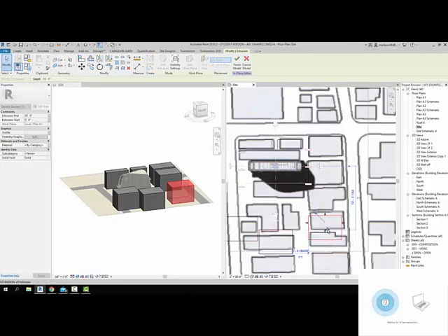So I'll just put this one in here. Okay, and while you have them selected, you can also change the height of them. If you want this one to be 20 feet, and maybe these are a little shorter, 15, and this one maybe 25, you can just adjust them as you need. I'm going to finish these, and when I come back we'll assign a material to them.